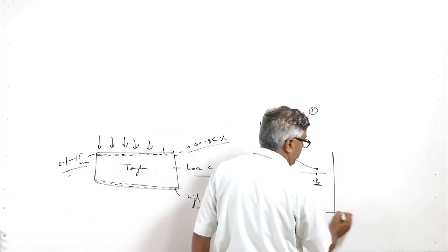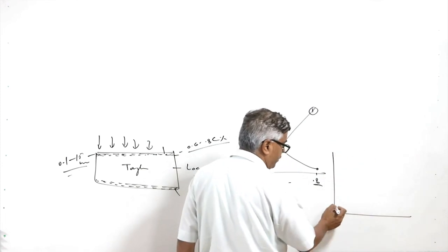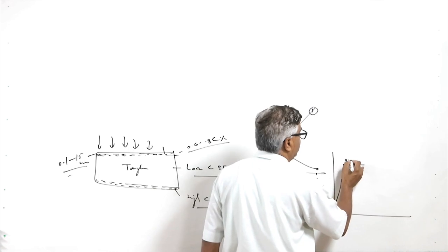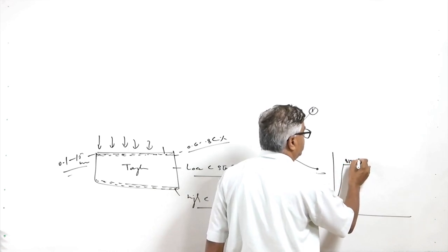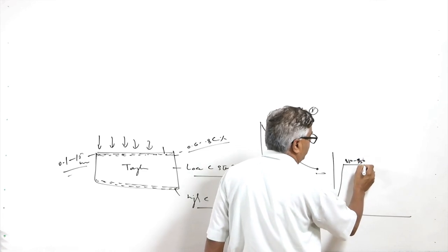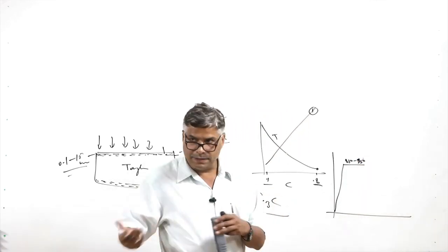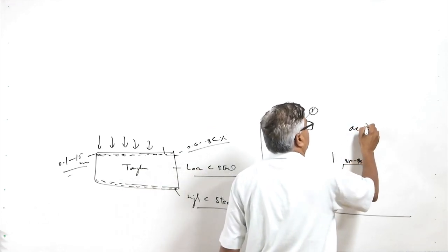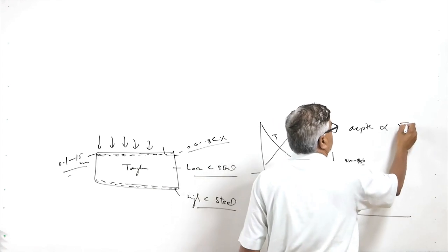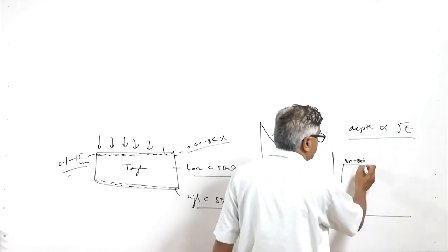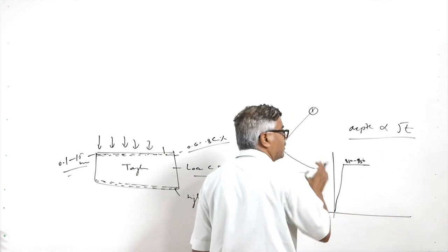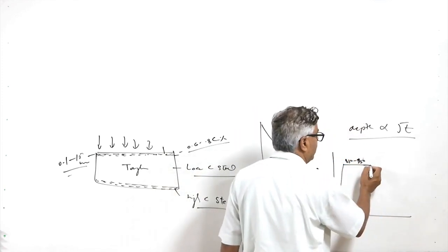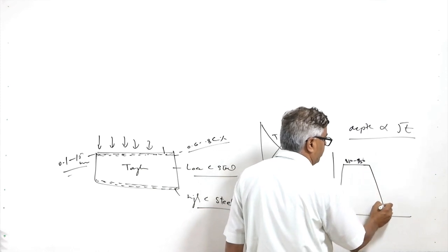That is why what we do, the kind of thermal cycle which is used for the carburizing purpose, increase in temperature up to the range of say 850 to 950 degrees centigrade, and it is held for the time as per the requirement of the depth to be modified, wherein depth modified or depth carburized is found proportional to the square root of the time. So longer is the time for carburizing, greater will be the depth which will be enriched with the carbon, and then it will be cooled.